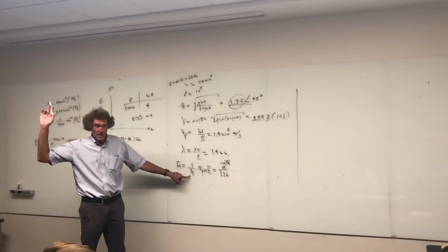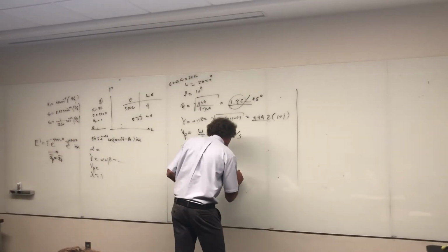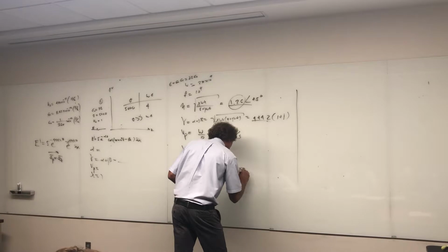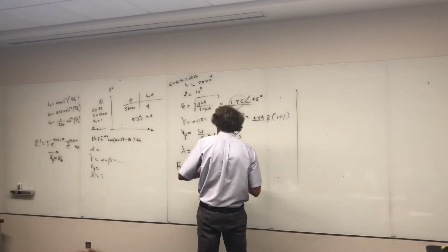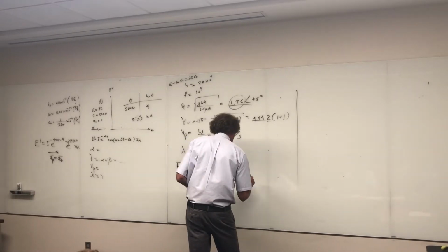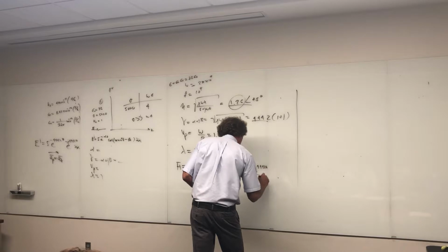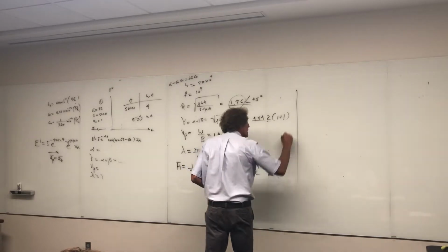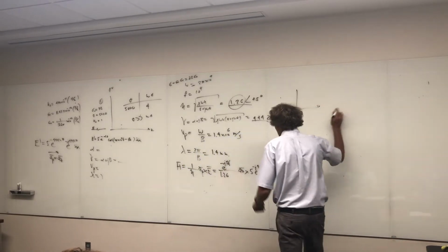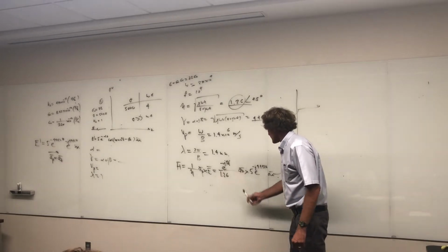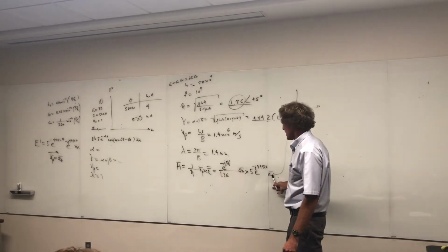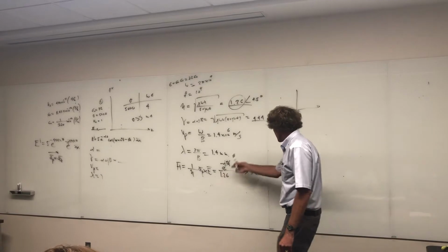You see this, guys? All right, now I take that, the unit vector in the direction of propagation is az, and I cross it with e. The e field right there is 5 times e to the minus j 4.442z in the ax direction. Come up here, and you can see really what happened. I have az crossed ax, which is ay. The rest is just grouping terms.